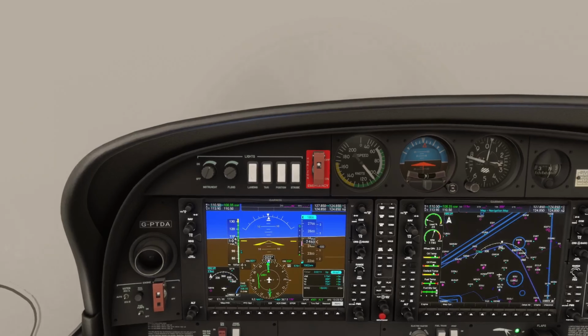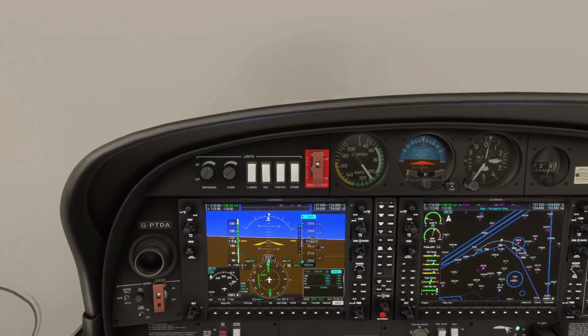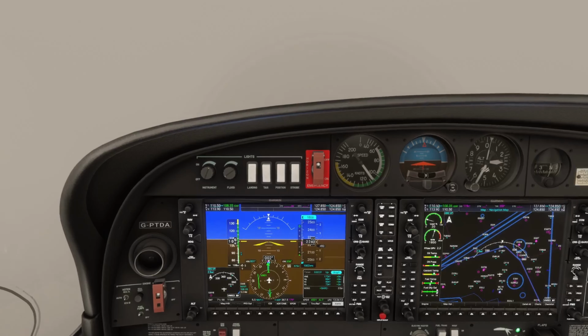So brakes released, undercarriage fixed, fuel balance sufficient for go around, landing light is on, T's and P's are in the green, hatches harnesses are secured.